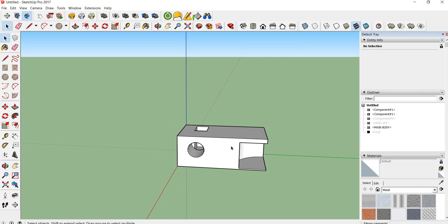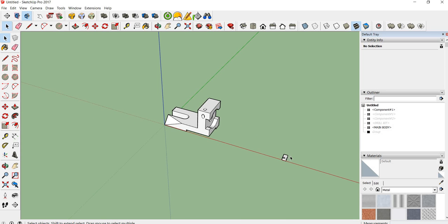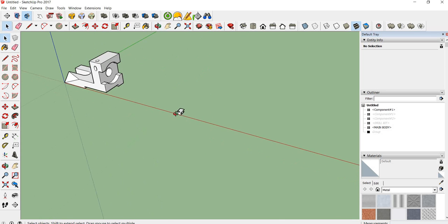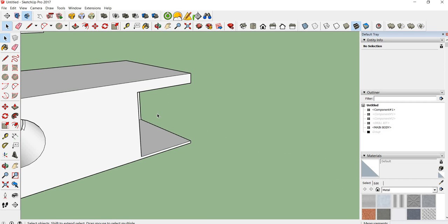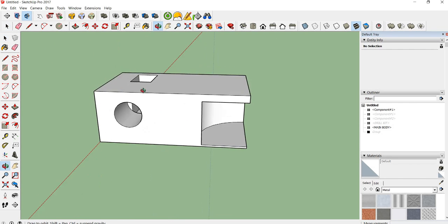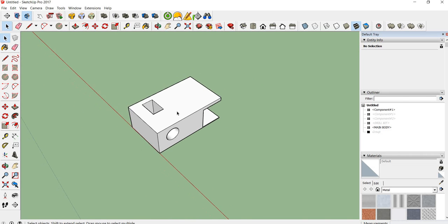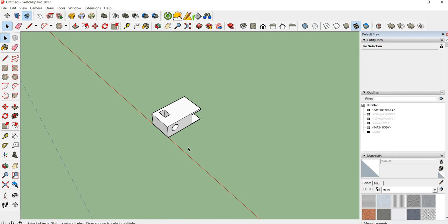Okay, great. So now what I'm going to do is I'm going to hide this, not completely delete it. Control Shift E to zoom extents. Whoops. And we're going to zoom in on this one right here. And look what was created. Everything I created in the giant component made it down here. So that is one way to handle things on a small level, is make a copy of the component, make it really large, do whatever you need to, and then delete that.